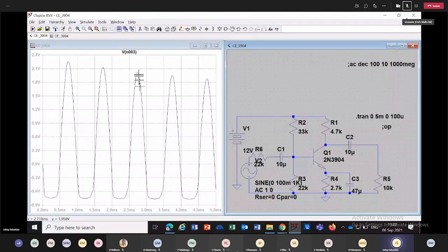So in the lab, while doing the experiment, you are getting a wave that is getting clipped on the negative side. It is saturation. So understand, at the output, if you are getting a negative clipping on the negative going signal, the amplifier is entering saturation.